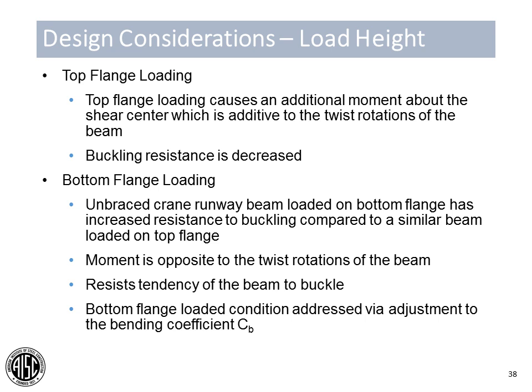If you can imagine, as your girder begins to buckle laterally, you get a small amount of deflection. The vertical load that's applied at this top flange as it deflects now has an eccentricity introduced into the system, which provides an additive rotational force, therefore reducing your buckling strength.